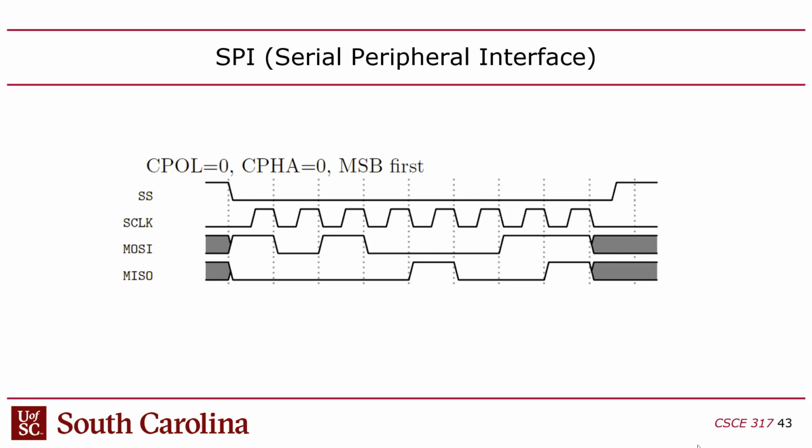In a digital circuit, when you clock data with a flip-flop, I know you guys didn't talk about this in 211, because this is more of an advanced topic we do in 611. But when you sample data, when you capture data using a flip-flop, you want to make sure that the data is stabilized before you capture it. It's got to be stable. You don't want the data changing too close to the clock edge or at the same time as the clock edge. Because if it does, you capture the data in a random state. It's called metastability.